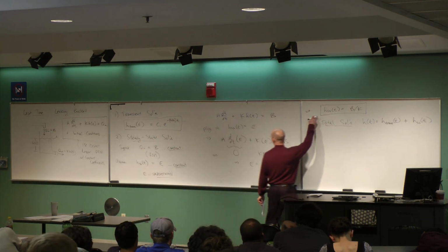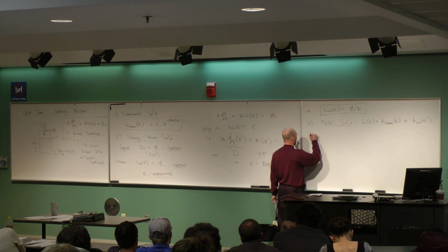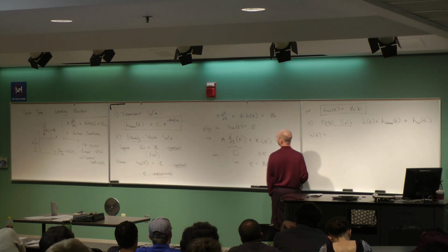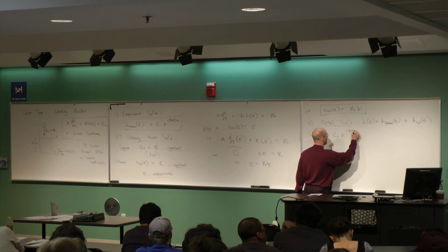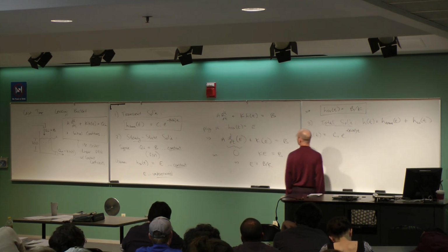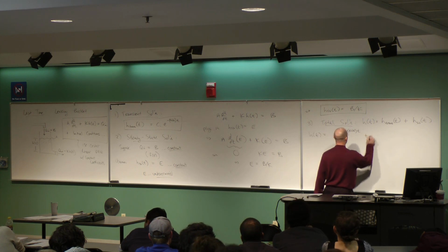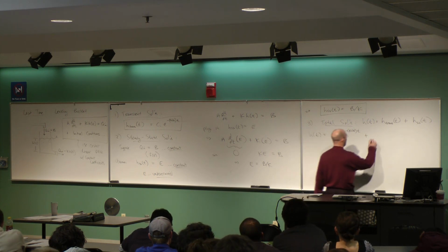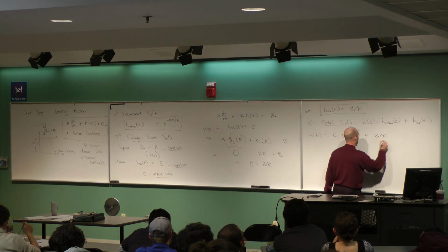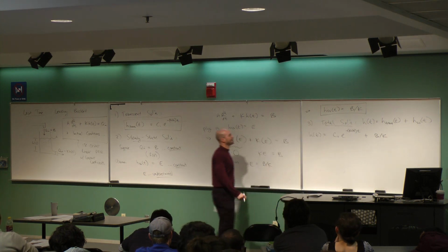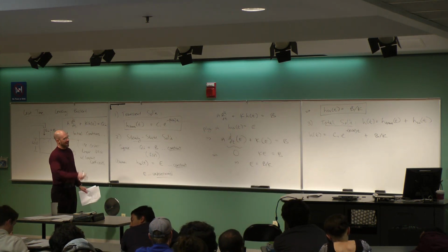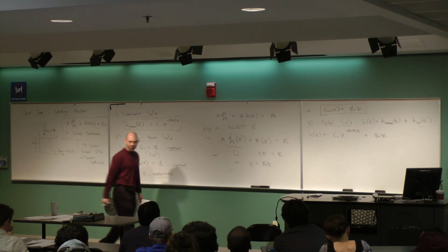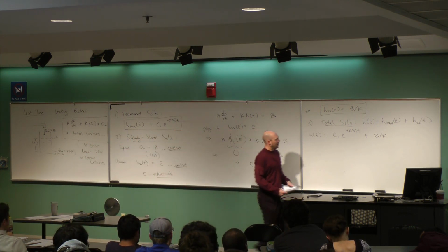So let's do it. We got the two. Okay, so this means that h of t is equal to, I got c1 e to the minus k divided by a times time, okay, plus I got h steady state, which is b divided by k. So again, whenever you work a problem with all these parameters in it, you want to take an inventory of your letters here and make sure you know what's what. What's the k again?